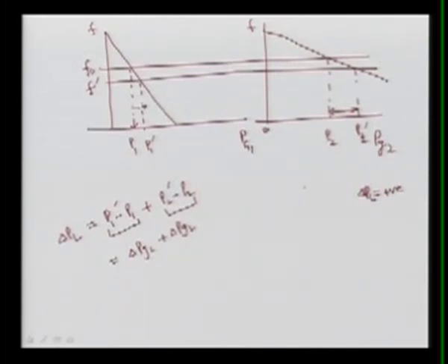Similarly we can go for the case where load is released, meaning some loads are set off, then the frequency will rise from the nominal. Here this is your nominal frequency, and we are starting from 0 here. In the sharing, the system frequency will be constant, and based on that we can calculate the loading of the system and generators, and they will take care of that. So you can see the change from P1 to P1 prime, and from P2 to P2 prime.